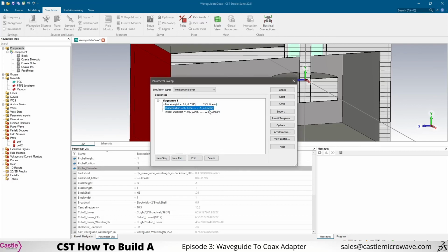Now this is going to definitely produce some very erroneous results that won't be suitable for what we're doing, but in order to just brute force this to observe what is happening by modifying these parameters, we'll just leave it as this. Now the reason we've gone for 5 for each is it's going to compute each variation between all 3. So this, if you do a quick calculator sum, will be 5 times 5 times 5, which is 125 results. Now this is why I recommended saving first, as this is going to take a little bit of time on your system if you are building along.